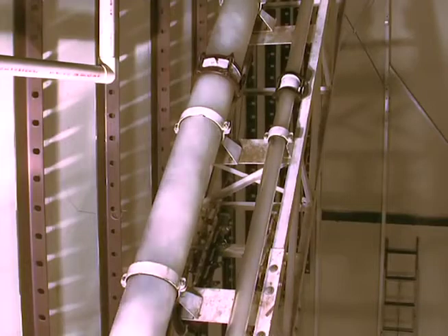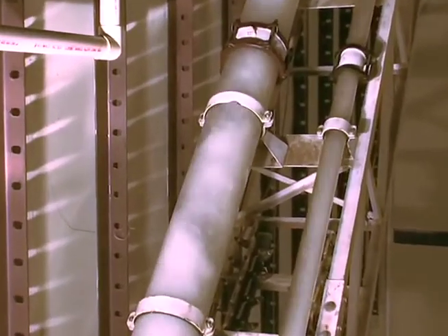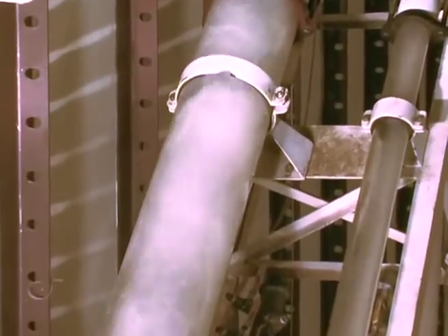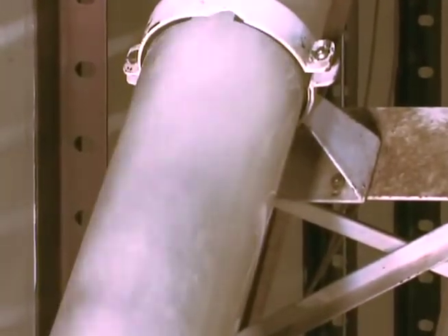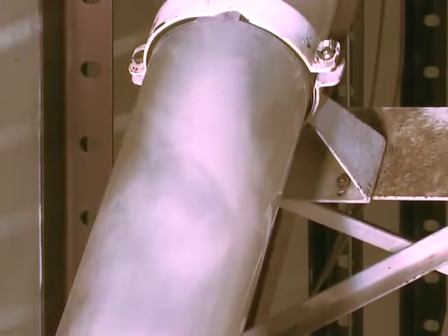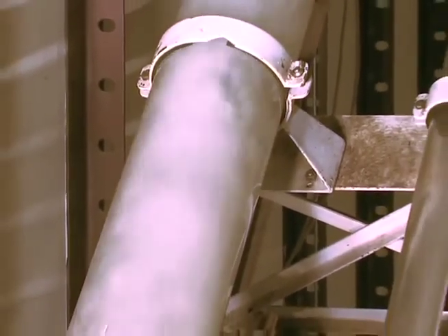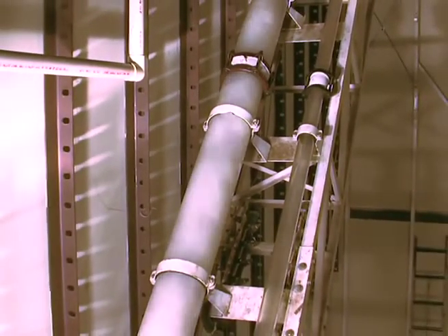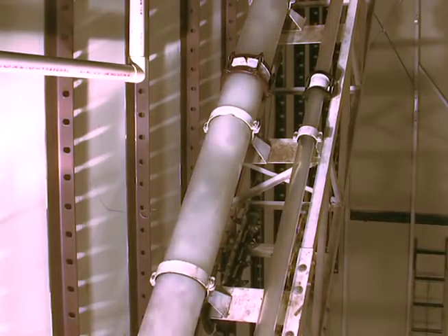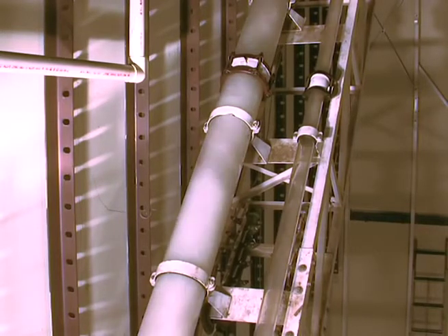This is a top view of the previous segment. The water rate is still 628 barrels per day and the air rate is 230 MCF per day. And you will see a series of pullbacks and close-up shots of the slug flow, particularly in the large diameter tube. In a moment, you'll see an interesting flow pattern where the slugs are moving by, but in between the slugs, you can see the water flowing back downhill until it collides with and is picked up by the following slug.